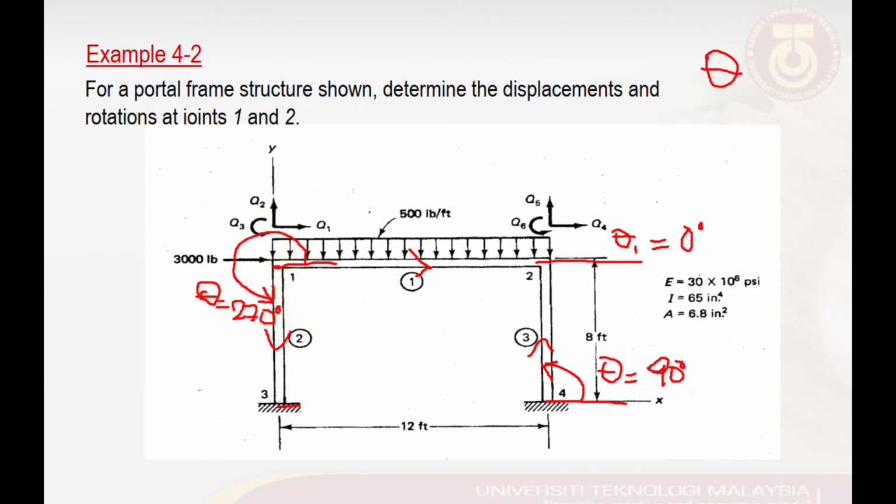So I will draw the line from where the connection starts. Then I start looping the angle until it reaches or finds the element. So in this case, we have theta equal to 270 degrees for element number 2. So this element connectivity is very important in setting up our element stiffness matrix.